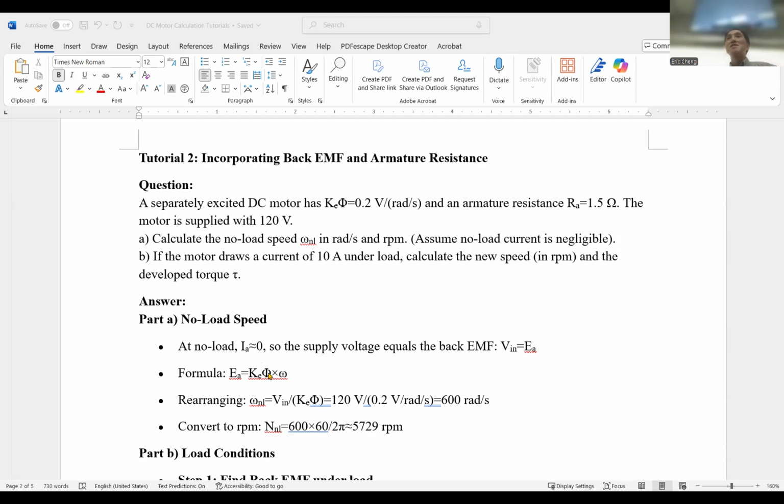Sheldon, did you implement that in your lab? How to estimate the torque constant using this method? Yeah. Okay, use a speed measurement and the voltage and current IA readings to get the back EMF constant and torque constant. Later we will look at how you set up the lab and discuss after the class. So that's one of the ways we can measure the torque constant.